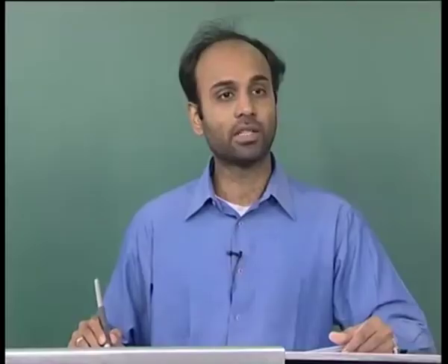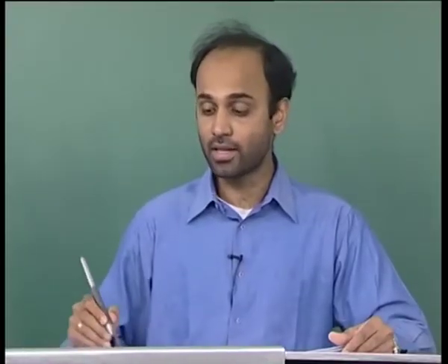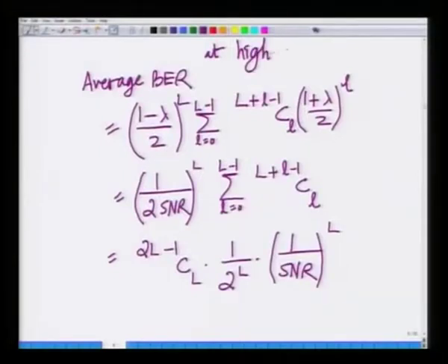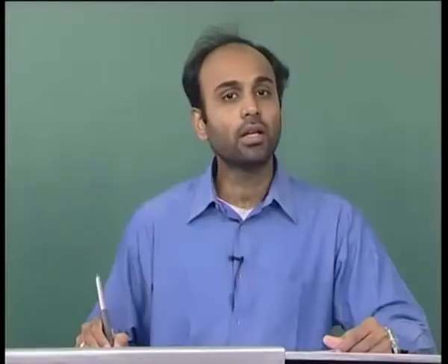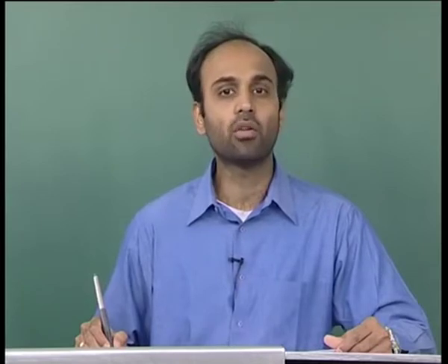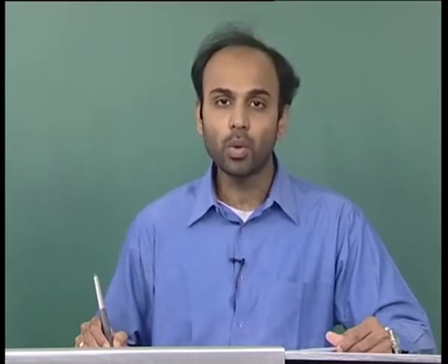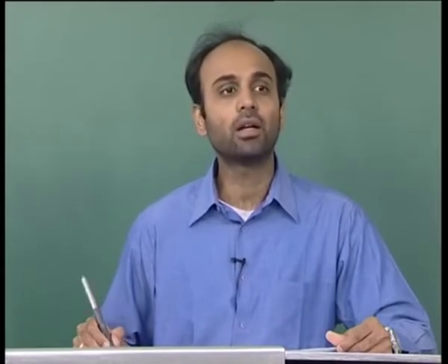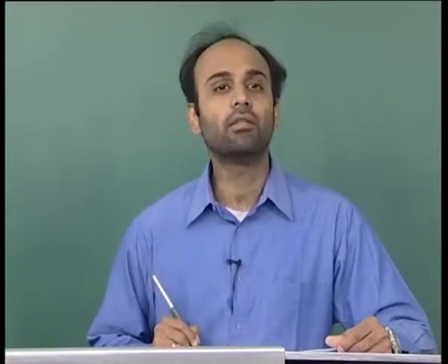Hence, the final expression for the bit error rate at high SNR, let me write it here, at high SNR, the final expression for bit error rate at high SNR is given as 2 L minus 1 C L times 1 over 2 to the power of L times 1 over SNR to the power of L, where L is nothing but the number of received antennas.